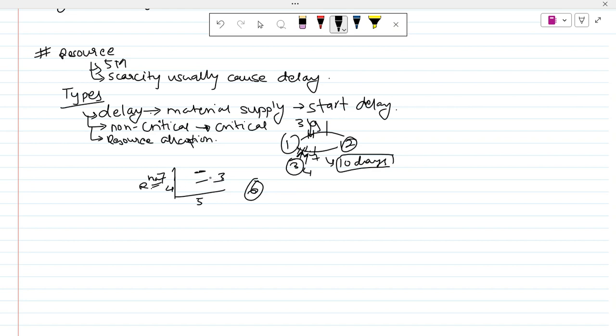So it depends on what is a critical time, what is a critical activity. If this is a critical activity, 4 days, we can shift 3 days if it doesn't make the other path critical. In our case, it makes other path critical activities, so we cannot shift the activity. There are other kinds of constraints also, like if this can be replaced using the preceding activity or succeeding activity. If this is possible, we can do that also.